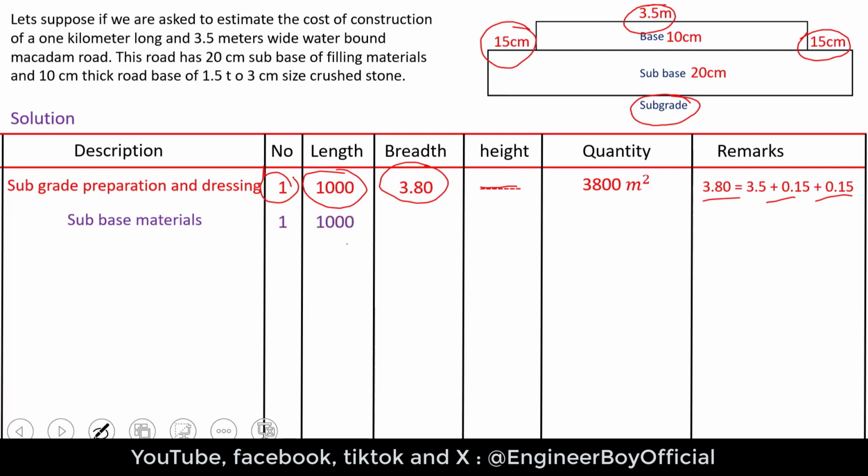The subbase width or breadth is just the same as subgrade, okay. However, there is a height which is actually 20 centimeters, okay. Now here is a point. I'm not going to take 20 centimeters. Why? The height should be something different, which should be 0.30. Now why? It is very important. As you can see, the 20 centimeters or 10 centimeters are according to the drawings, which means they are already considered as constructed road, okay?